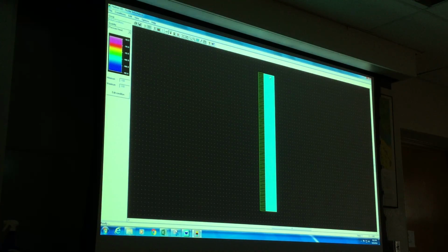Since we impose a constant flux, we don't need to do anything with the top boundary. It's really only when you have, like in 1D, a constant pressure boundary that you need to specify it together with the initial conditions. But now we say the soil profile has a moisture content equivalent to a potential of -100 centimeters.